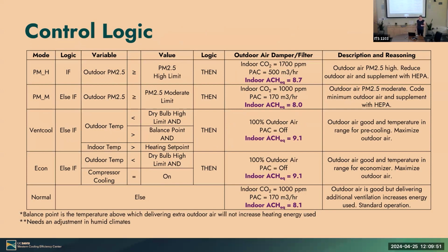At the end of the day, what I'm trying to do is achieve indoor air change equivalent for respiratory aerosols, meaning that there's a new ASHRAE standard for reduced infectious disease transmission. And essentially the goal is, we're all exhaling these respiratory aerosols, let's get them out one way or another. We use outside air or filtration or a portable air cleaner, and those things working combined. I'm trying to achieve an air changes per hour of like 8 to 9 air changes per hour in the classroom, regardless of what mode we're in and what's going on.